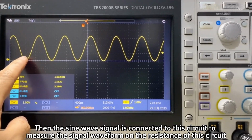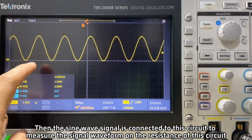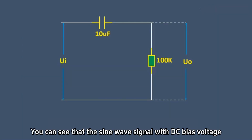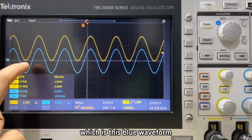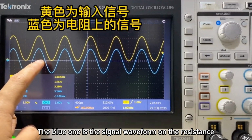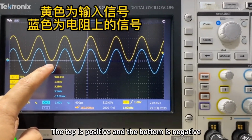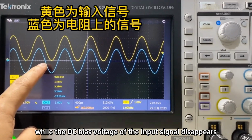Then the sine wave signal is connected to this circuit to measure the signal waveform on the resistance of this circuit. You can see that the sine wave signal with DC bias voltage, after passing through the capacitor, only has an AC signal left, which is this blue waveform. The blue one is the signal waveform on the resistance. The top is positive and the bottom is negative, while the DC bias voltage of the input signal disappears.